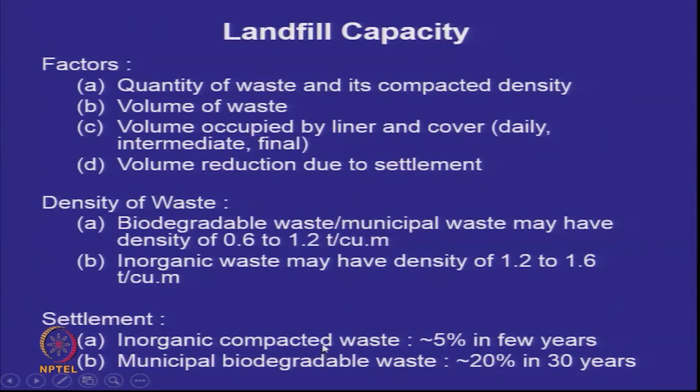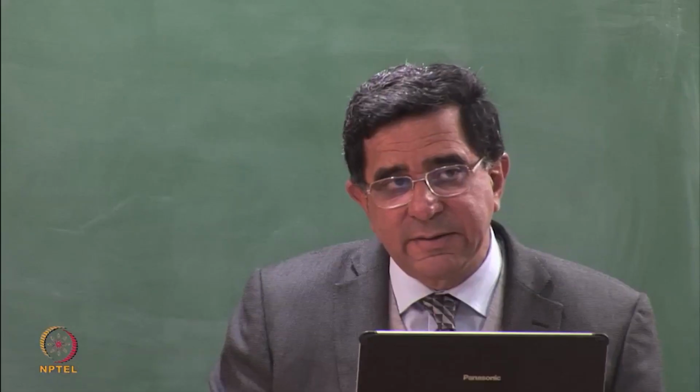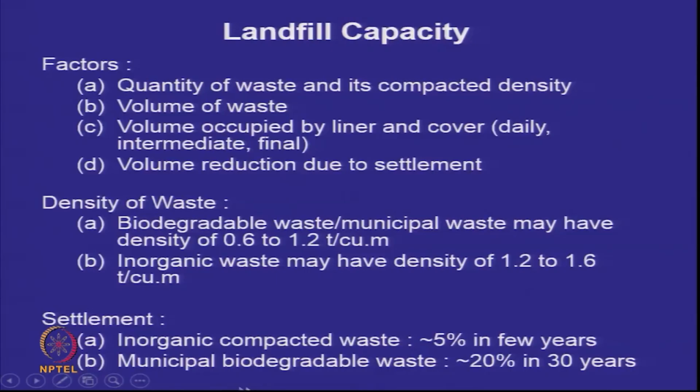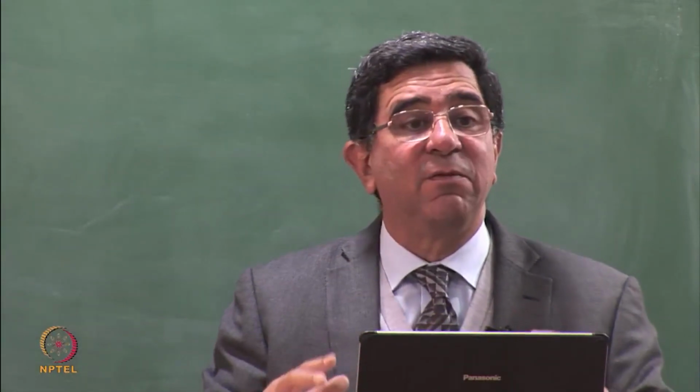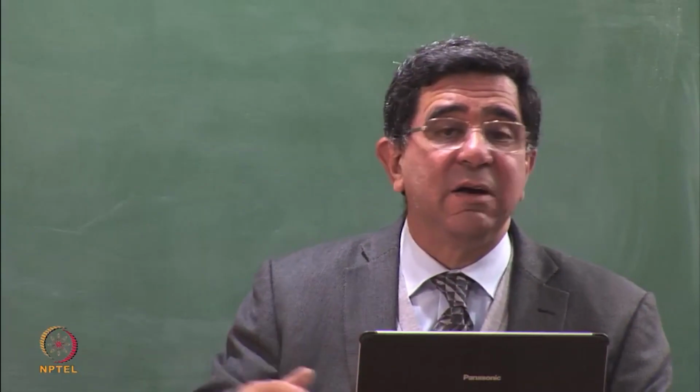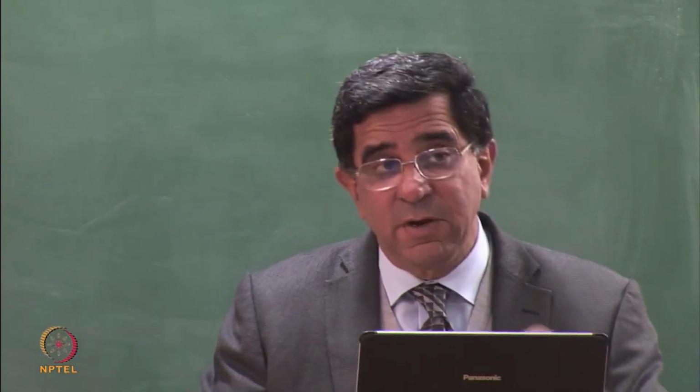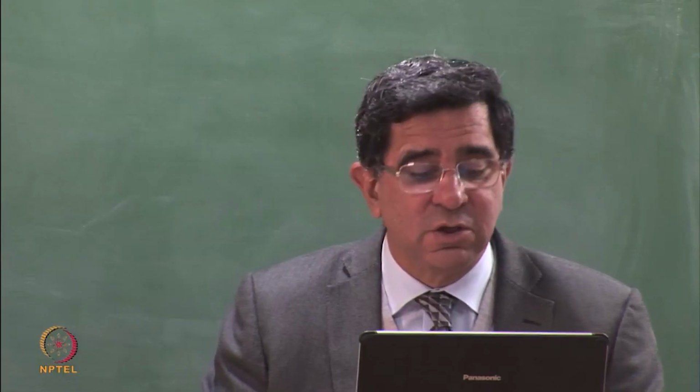If you have inorganic compacted waste, the waste is not going to settle much, and you are not going to get more airspace, especially if you have compacted it properly; it might settle by a few percent. So, do not rely on this additional capacity. The municipal solid waste does give you settlement, but not in the first few years. The biodegradation process actually slows down because you have put a cover. So, when we talk about getting 20% or 15% settlement in municipal solid waste, we are talking of it happening over 20, 30, 35, 40 years. So, you have to be very cautious if you are going to take that volume in your area computations.